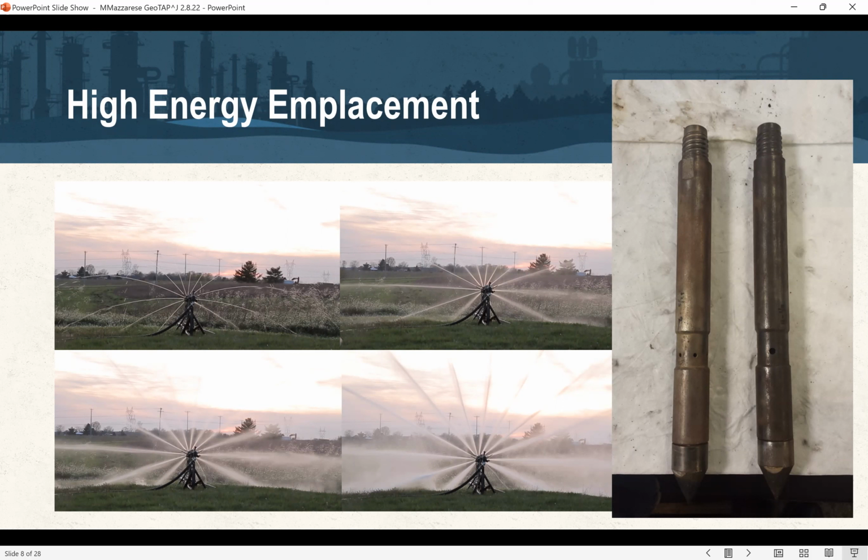The system you see here is the one we use primarily for bedrock applications or deep overburden applications, and it's capable of going up to 300 gallons a minute at about 2,500 PSI. That's overkill, obviously, for a relatively shallow application, but if we're injecting in fractured bedrock, or in weathered silt claystone at 50 feet, we may bring out this larger injection system.